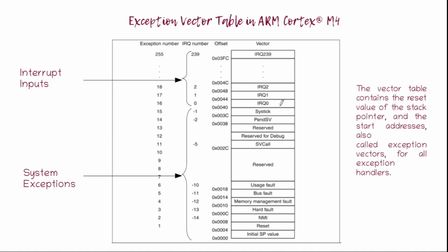One added benefit of this is you can program entirely in C without having to get into assembly coding, because since these are just address locations, you can create a data structure in C and allocate it to this memory location through your linker without having to write any assembly code.